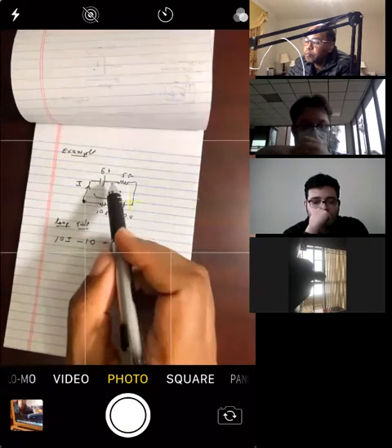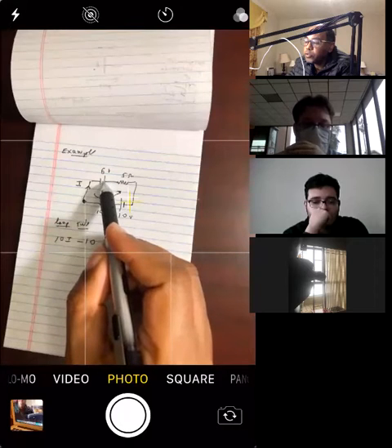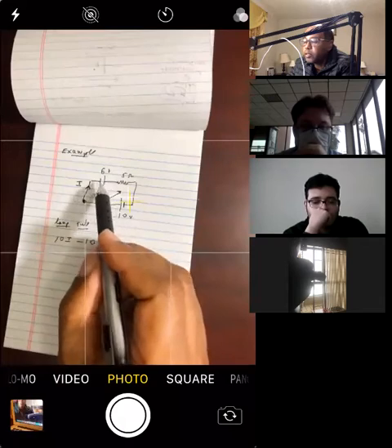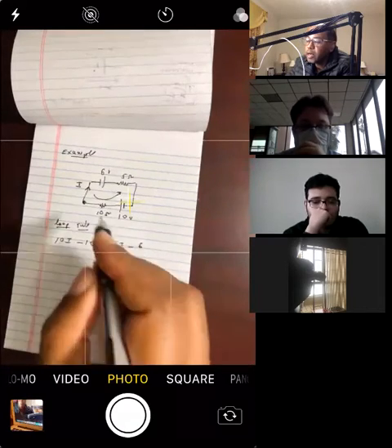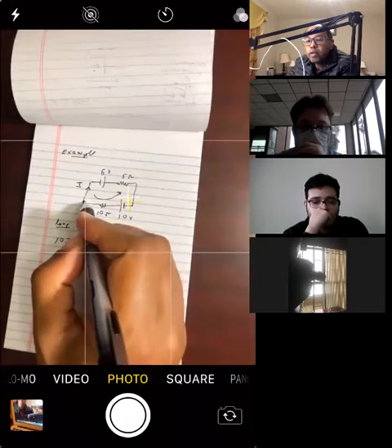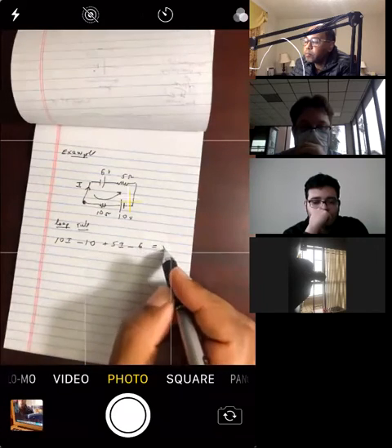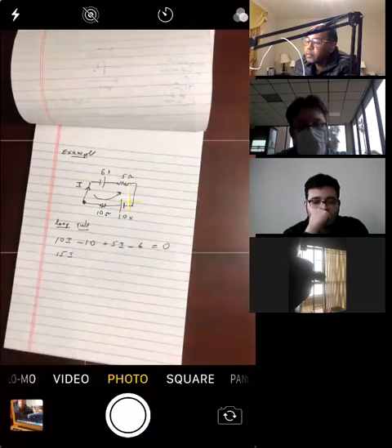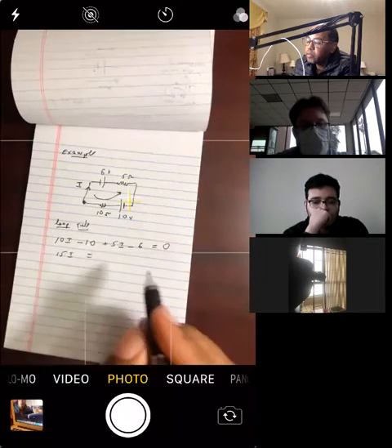I keep going. Now I'm going from positive towards negative. This is also negative, okay? Because I'm going from positive to negative, right? So it's going to be minus 6. I come back to my original point. I have added up all of them. I equate this to 0, okay? So I've got 15 I's, and then I've got 11 on the other side, okay?